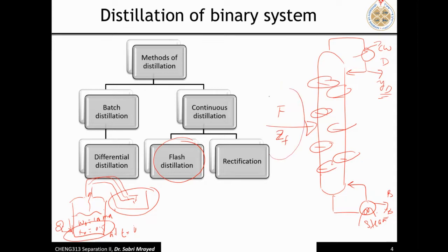Now you are constrained, so you have constraints, and one of them is the material balance. You have to ensure the material balance is okay. And also the equilibrium stages, which are going to be assumed to be equilibrium stages. And for each stage, you're going to have Ki, which is K1 and K2 for a binary system, for each stage, because you're going to have different K values since there are different temperatures.